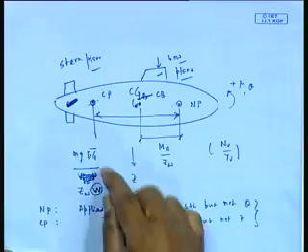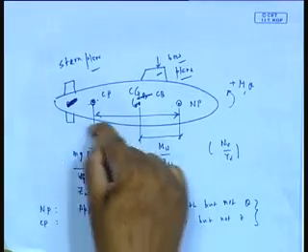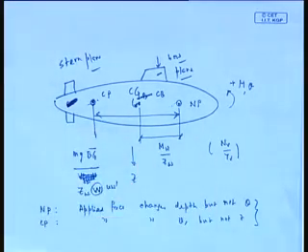The main difference is, you should notice, the existence of the hydrostatic force. You are going to ask me, there should be hydrostatic force in a ship also. Of course, not in the rudder plane, because in the plane where you are doing this, there is no hydrostatic restoring force. But here in this plane you have a hydrostatic restoring force. So it's a question of competition between hydrostatic force and dynamic force.